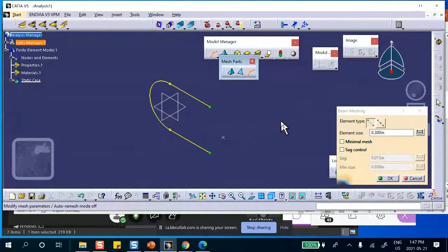Now beams are very versatile, and very big beams can do an excellent job for transferring loads. The problem is that if I put too big a value here, for example 3, then there is going to be one element here and one element there, and this is going to cause a problem.